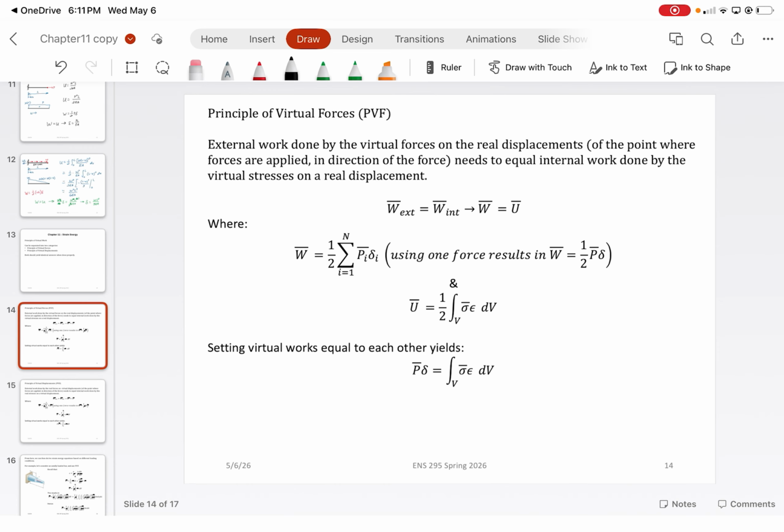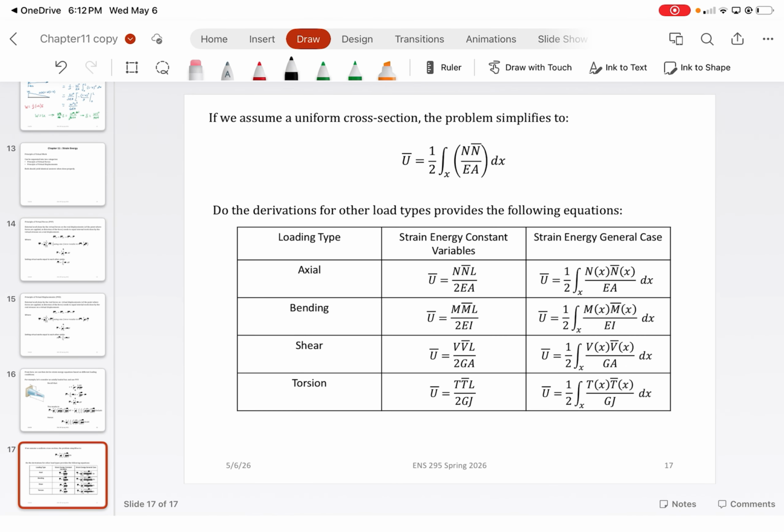It's the concept of virtual forces and virtual displacements. It's not an actual force that's being applied, but a characteristic or dummy force, for example, that would be applied. That's actually how you would be able to find deformations at any given point. And what you would find is that the expressions are entirely similar to what we had previously defined, just now one is characteristic of the virtual location.